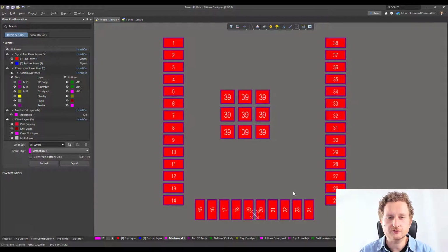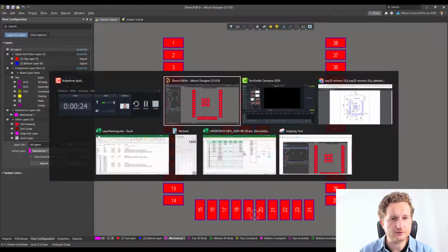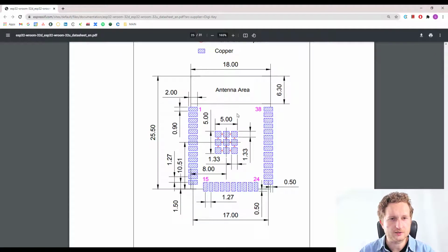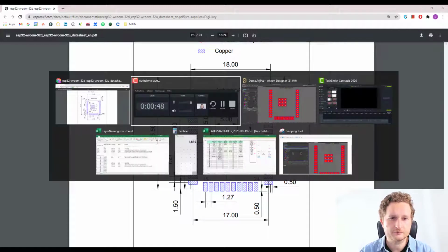Okay, before we edit those several layers with the additional information, as I mentioned early in the tutorial, we have to move the complete component in Y direction, because as you see, our origin is right here at the bottom, but it must be at the center of the module. So let's double check again in the datasheet. In X dimension it's currently centered, so we don't have to take care of the X orientation, but the Y orientation is at 0 right here, and we want to use the middle of this dimension here.